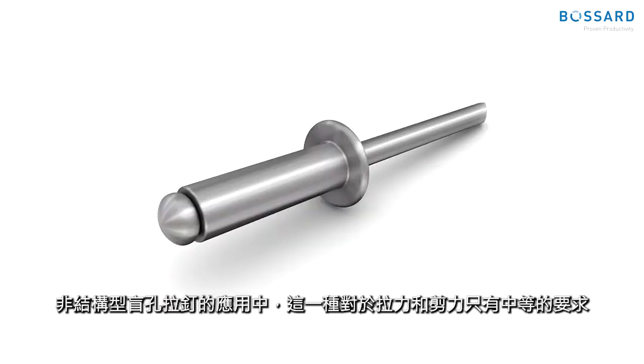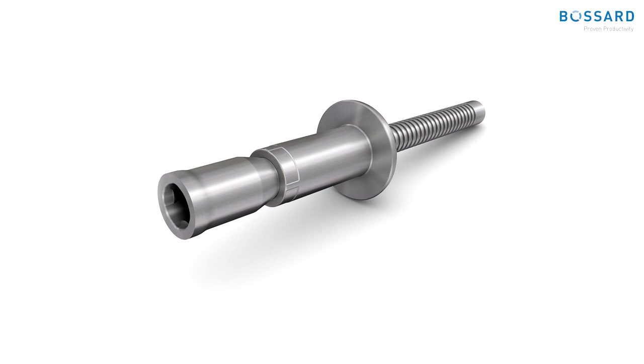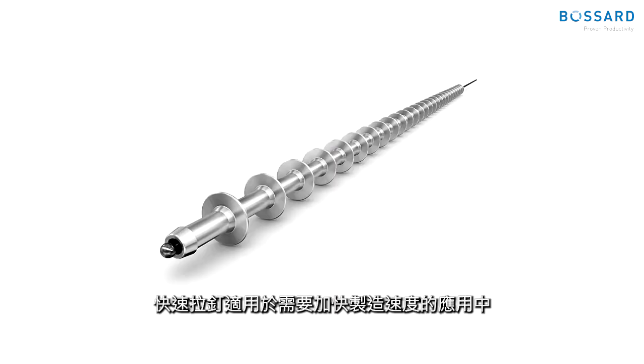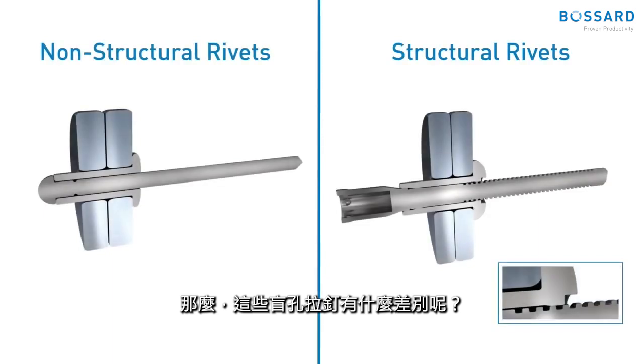First, non-structural blind rivets for applications which have a medium requirement in regards to tensile and shear forces. Second, structural blind rivets for applications which have a high requirement in regards to tensile and shear forces. Third, speed rivets for applications where manufacturing speed is needed, with low requirements in regards to tensile and shear forces. So what's the difference between these blind rivets?